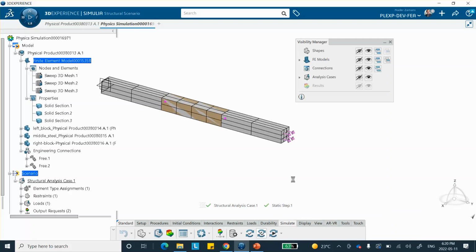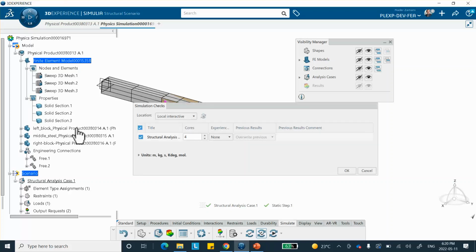This is if you have some obvious errors that are going to pop up in the model and scenario check. We're going to see it ahead of time before it runs. So make sure you have your engineering connections when you do this tie detection. And the key was that you have to ask for find the ties in that radio button.